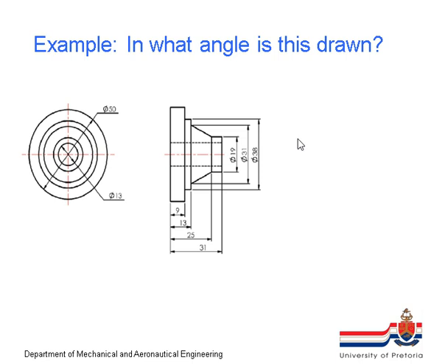If I viewed it from the right-hand side, I would see the outside big circle, that smaller circle, the big side of the cone, the small side of the cone, which is the same as that little cylinder on the end, and I would see the hole in the middle. So now the question is, what is this? Is this component seen from the left, or is it that component seen from the right?